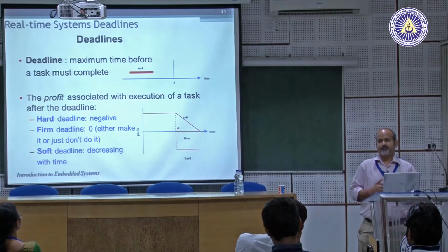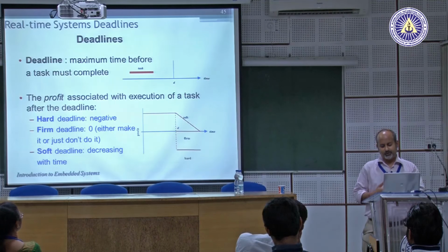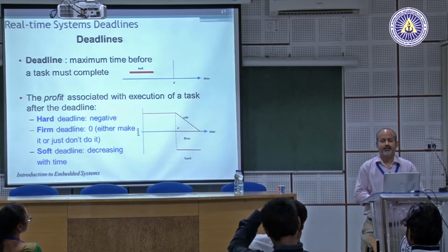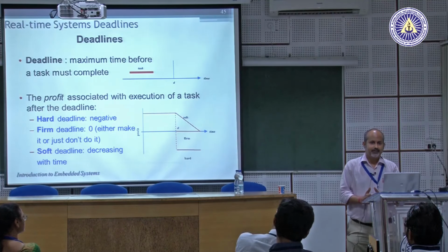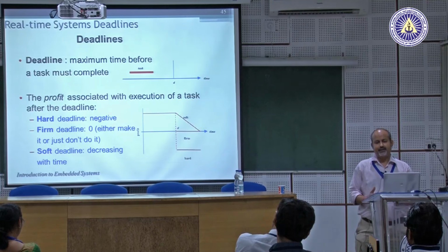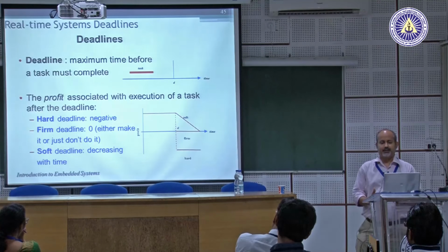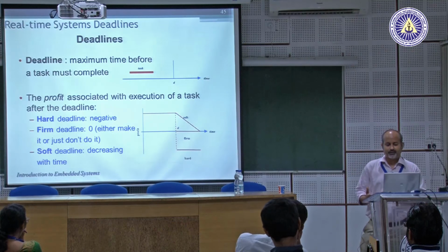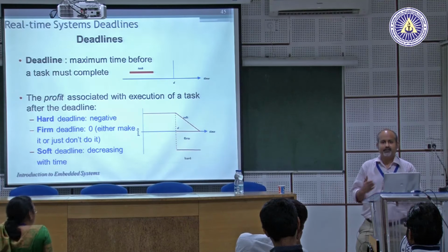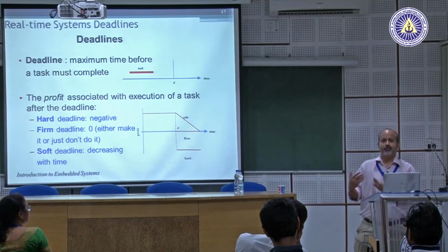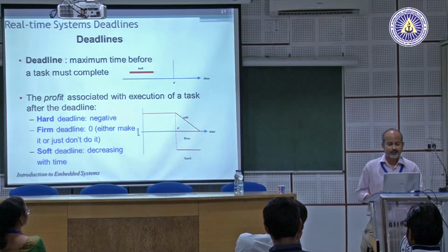And for each repetitive task, you kind of know when the task is going to be starting to execute. It's usually periodic, and then you have deadlines, right? Because the deadline is a function of the application. For video processing, for example, if you are going to have a video of 24 frames per second, then you know 1/24 would be your deadline, your absolute deadline.